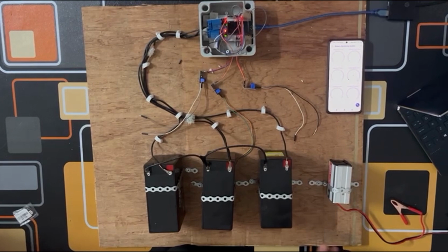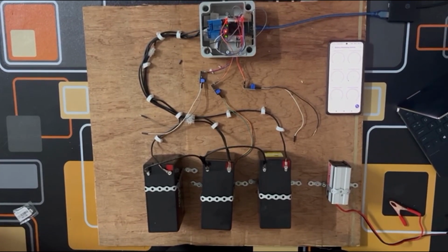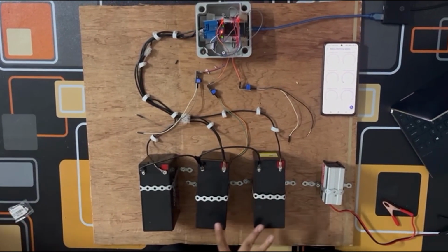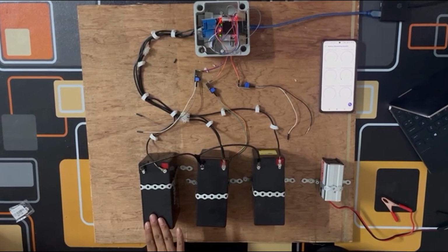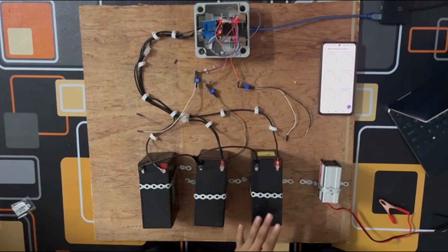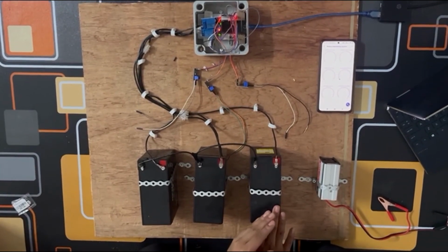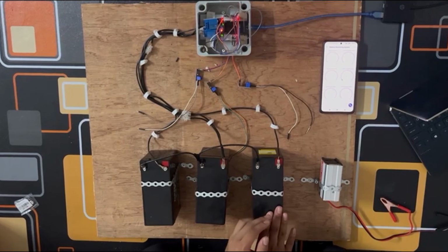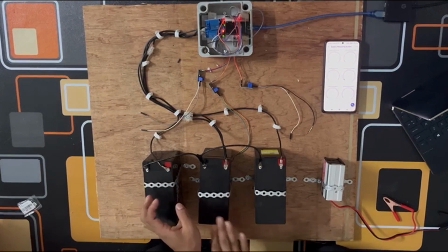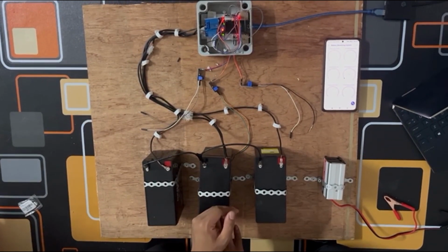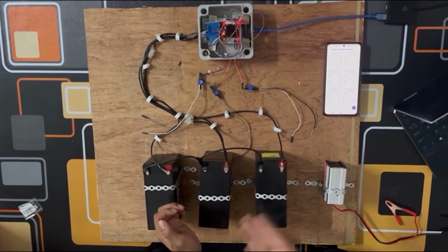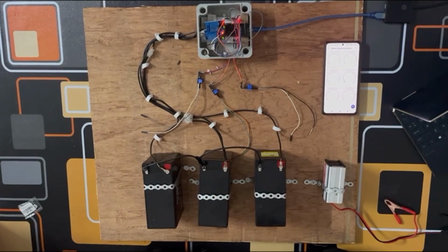Assalamualaikum and good morning. This is the IoT for balancing and monitoring the percentage of the battery. Firstly, we use 3 batteries, which are 2 batteries from solar and 1 battery from the hydro. In this case, if the first battery percentage is lower than 25, the second battery will support the first battery to get up to 25, and then if the second battery is less than 25, the third battery will support it to get up to 25. Why do we do balancing like this?